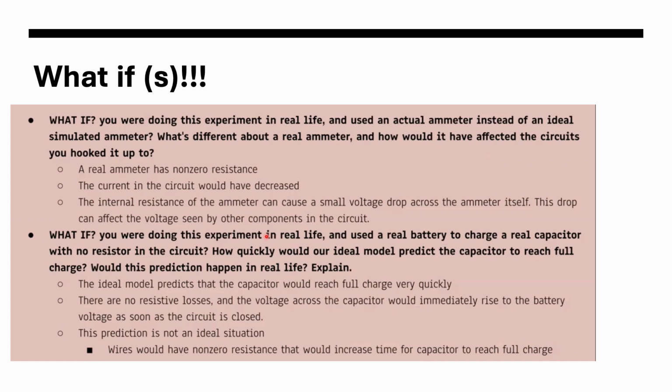Now, what if you're doing this experiment in real life and use a real battery to charge a real capacitor with no resistor in the circuit? How quickly would our ideal model predict the capacitor to reach full charge? Would this prediction happen in real life? Well, the ideal model predicts that the capacitor would reach full charge very quickly, as there are no resistive losses, and the voltage across the capacitor would immediately rise to the battery voltage as soon as the circuit was closed. So the prediction is not what would happen in a real situation.